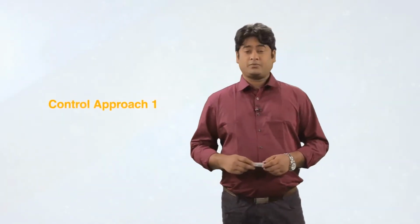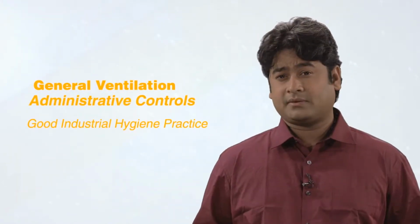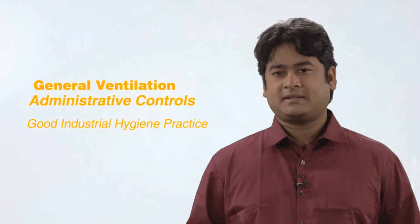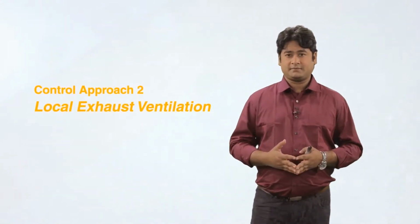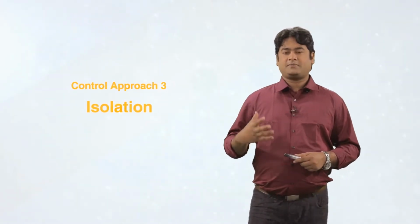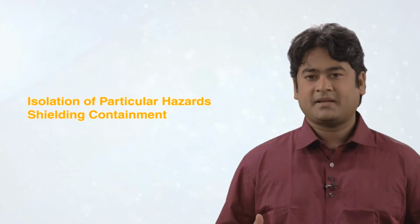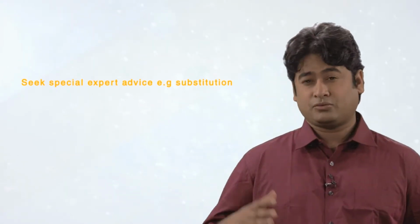Now we will see what these control approaches 1, 2, 3, 4 mean. Control approach 1 means general exhaust ventilation or administrative control, a good hygiene practice within the workplace. Control approach 2 means local exhaust ventilation. Control approach 3 means isolation of particular hazards or containment of particular hazards within the process. And control approach 4 means seeking the advice of an expert to substitute the hazardous chemical with a less hazardous chemical.